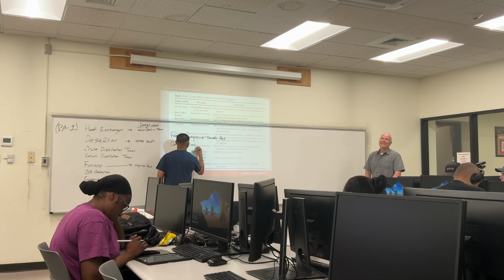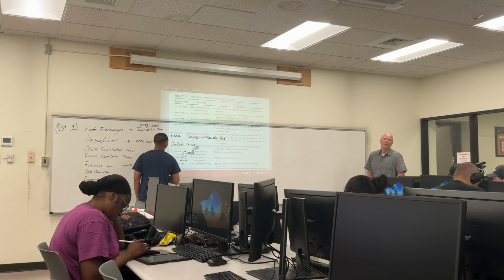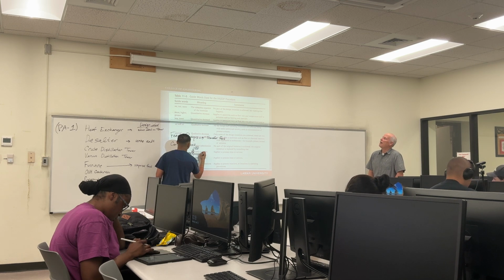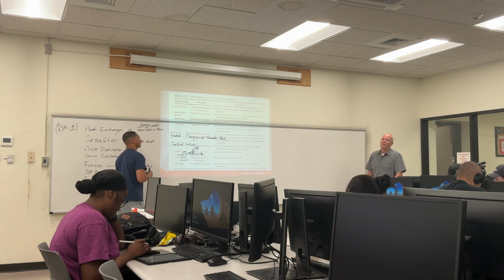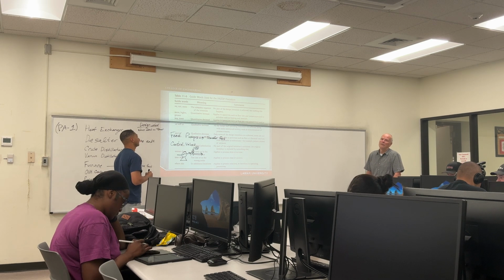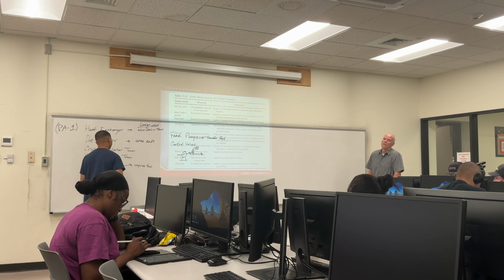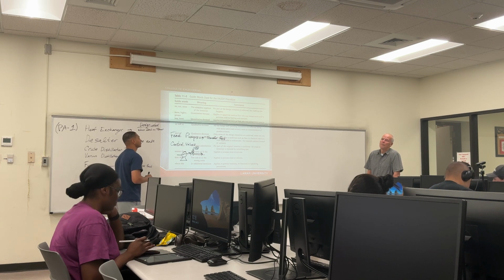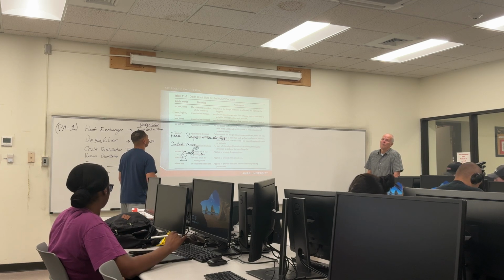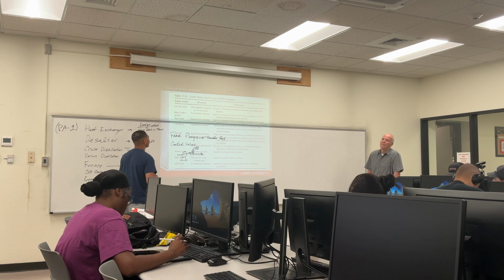Okay, the design intent of that system is to provide feed, okay? So, no, or none. What bad could happen? Where's that feed go? And what bad could happen if we stop providing it? No flow, no feed. What bad could happen? The tower. So the boilers are just gonna start heating up the tower with nothing else to heat, so you're gonna cause some structure failure.